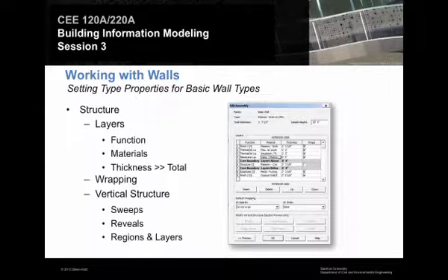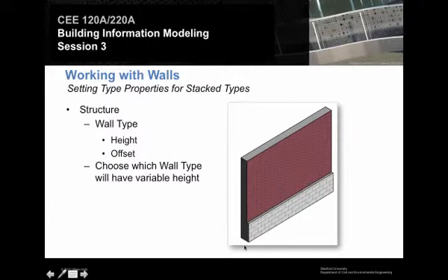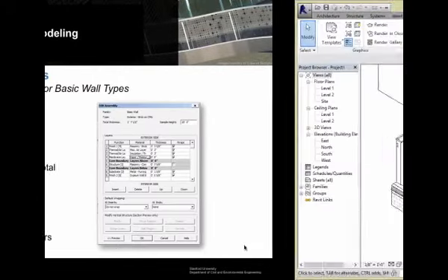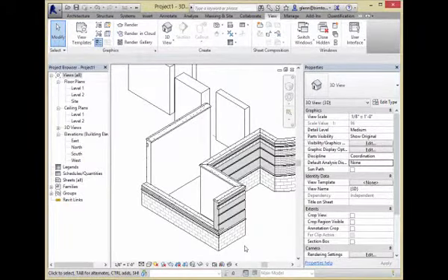The way we create new wall types or new floors is the same. We go in and we change the structure. You can say it has different layers and different materials we want to work with. Okay? And then we have that in our collection of different types we could apply. So let's take a look at the structure of one of the walls that are built into this little library or the sample project.